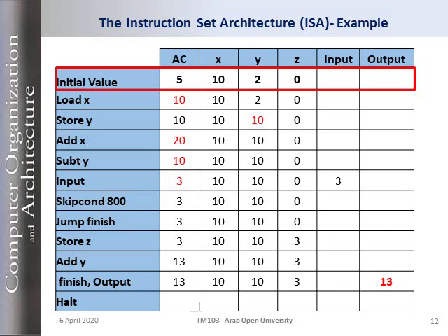So we'll start with Load X. Load X means, if you remember, this is instruction number 1. Load X means to get whatever value is stored in memory location number X and put it in the accumulator. So what is stored in X? It's 10. So 10 will be stored in the accumulator. This is what Load X does.